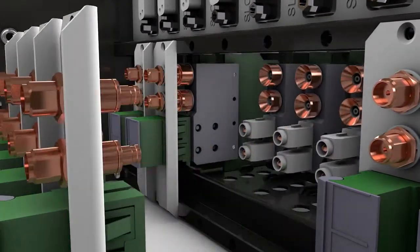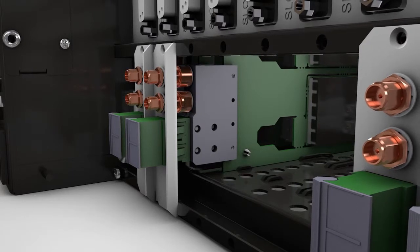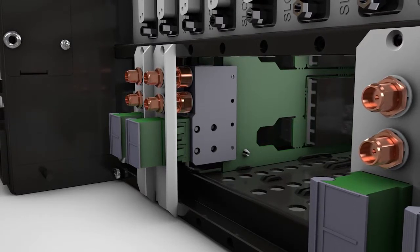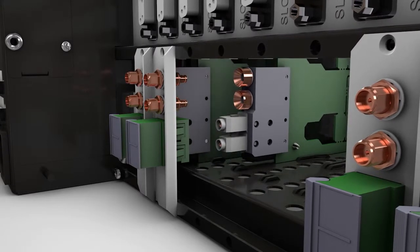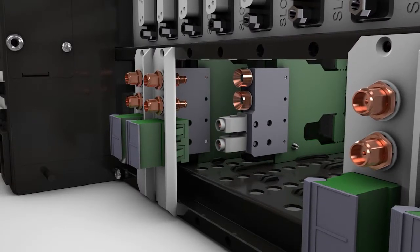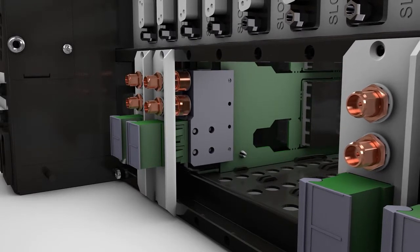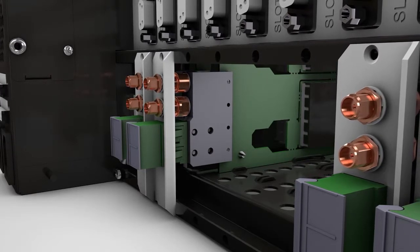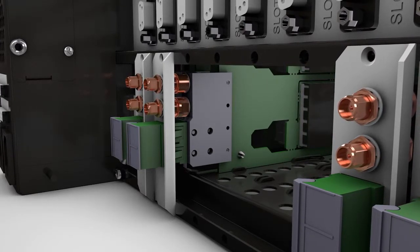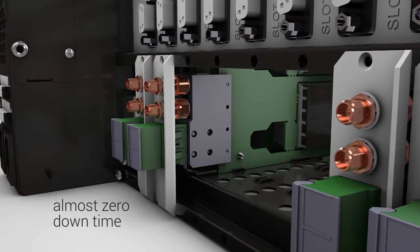The option of blind mate connectivity means RF and optical connectors are captive in the chassis backplane. To change a module, you can simply slide it out and replace it without any rewiring. This reduces the risk of damage to cables at the rear of the installation. The SNMP module can automatically upload the saved settings of the previous module to the new module, enabling rapid hot swapping and almost zero downtime.